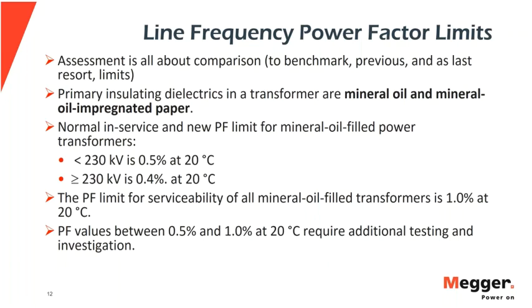Now, as far as the power factor limit for continued serviceability, can I keep this transformer in service or not? That's 1% at 20 degrees C. Any power factor results you measure between 0.5% and 1% are generally looked upon as, hey, this requires some additional testing and investigation.